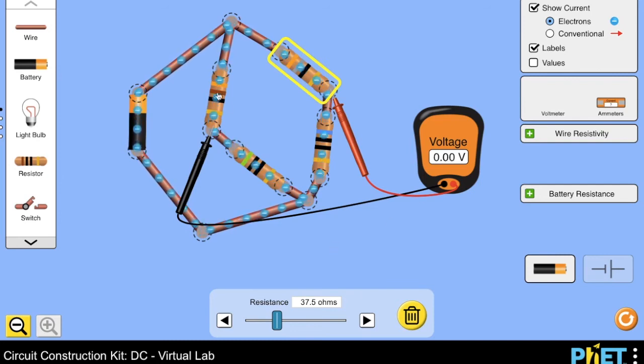So after changing the resistance of R1 and varying the resistance of R3, over here we have reached a potential difference between these two bridges equal to 0, meaning that there is no current flowing between these two points, and therefore our bridge is balanced. Now what we are left to do is determine a value for Rx. By clicking on Rx, we can see that its resistance is equal to 60.5 ohms.